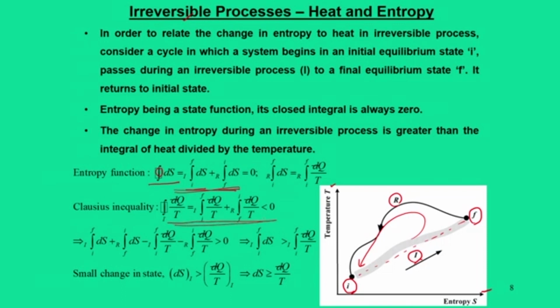And now for the element we write the entropy change, that is equal to the final entropy minus the initial entropy, for only dV. Once we find this for the element dV, with temperatures Ti and Tf, the entropy first, then we can integrate this from x is equal to 0 to x is equal to L, which will give you the entropy change of the system. This is the analysis to do problems where we calculate entropy change, where the system goes from a non-equilibrium state.